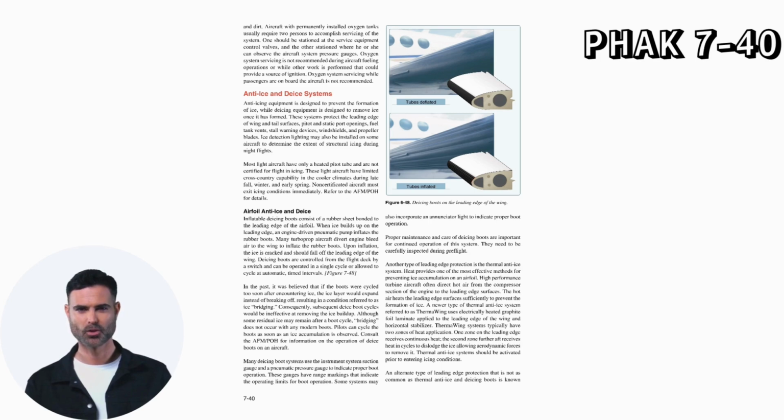De-icing boots are controlled from the flight deck by a switch and can be operated in a single cycle or allowed to cycle at automatic, timed intervals. In the past, it was believed that if the boots were cycled too soon after encountering ice, the ice layer would expand, instead of breaking off, resulting in a condition referred to as ice bridging. Consequently, subsequent de-ice boot cycles would be ineffective at removing the ice buildup.